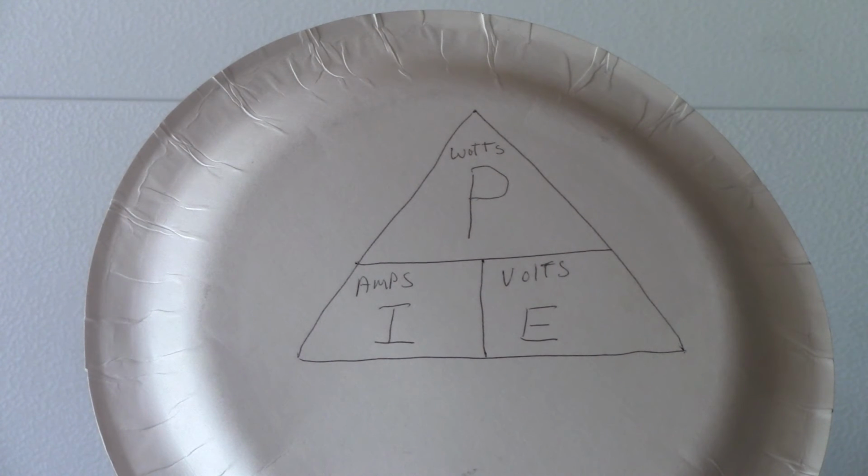Remember, you never want to burn more than 20% of your battery. You just don't. If I've got those 6,000 watts in those two tanks, I don't want to drop them down below 5,000 watts because you're going to shorten the life of your batteries when you do that. So when you're calculating battery size, that's where Watt's Law comes in too. How much do you want to use versus how much battery potential do you need?